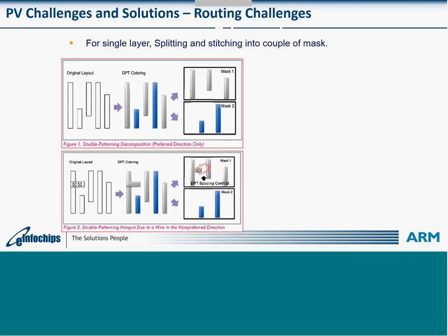More is split stitching those as well, but that is easy for foundries. So basically TSMC doesn't follow that as strictly. So we have to restrict our router itself not to drop such jogged wires. Our tools were not really capable enough to understand every rule of double patterning, and there had to be a lot of manual intervention at that time.